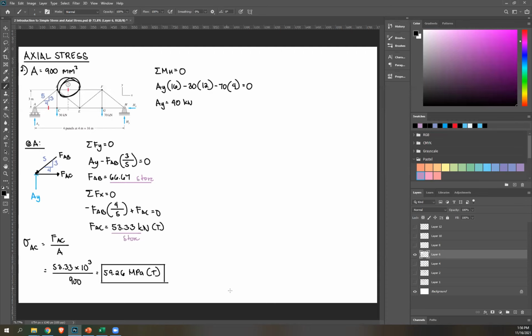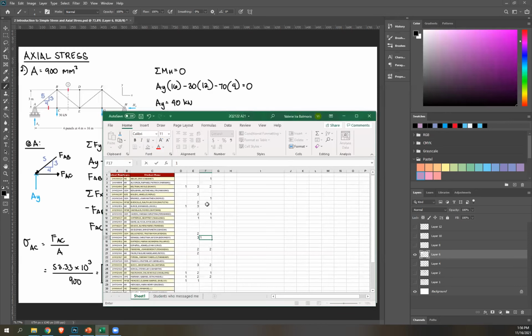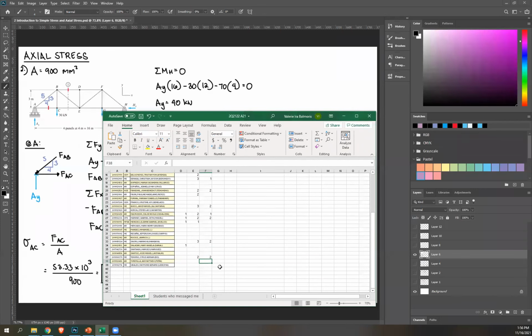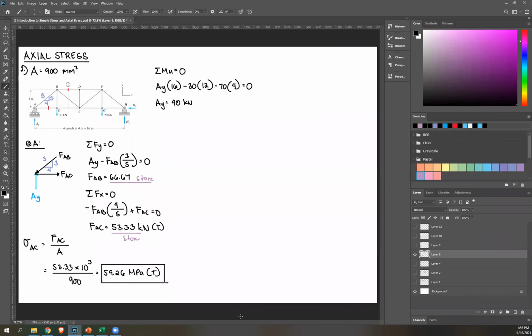This is your stress BD. Okay. Now the question is, should I use method of joints or sections? Please answer in the chat, joints or section. Correct. Okay, so you can use both. Technically, you can use both, but it's easier to use method of sections.